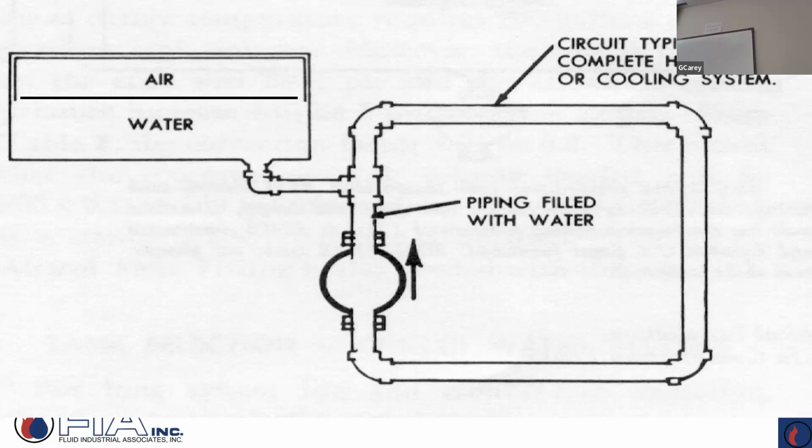And he says, if I was to draw here and put a boiler there, and I turned the boiler on so the boiler started to heat the water, what would happen to the volume of the water in the system? It would increase. And where is the only place that volume of water could go? Where the gas is, right?